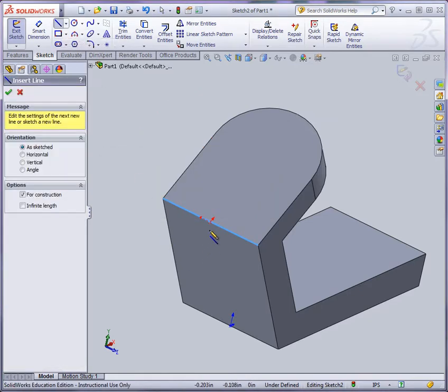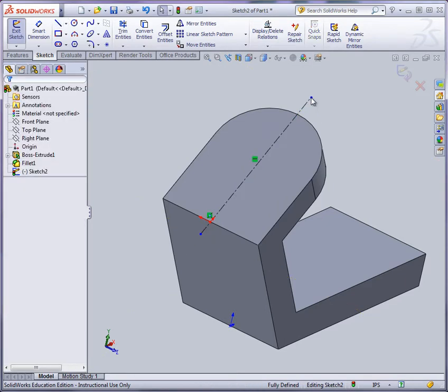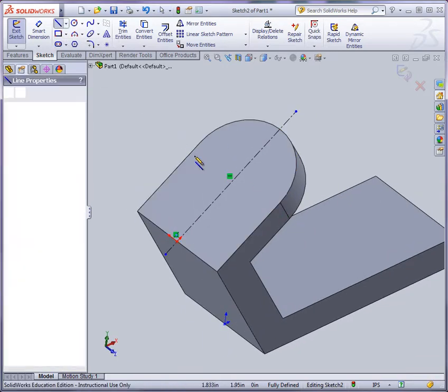We'll use a center line, and notice how we can just create an extension line right off the midpoint there. If I start just off the face and then create the vertical line like that, now it's aligned with the face and centered. No need for additional dimensions or other geometry. The other thing that we could do here is now we could create the horizontal line.